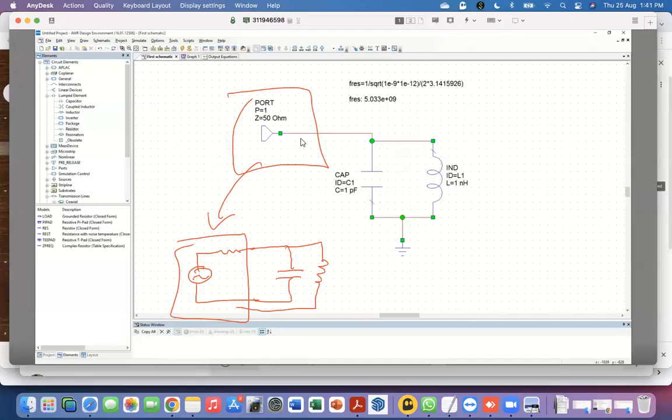Initially, when the energy is getting built up, there will be some reflection and some absorption, and the reflection will not be exactly 1. It's only after it has reached a steady state, which will correspond to whatever the voltage source value is and the 50 ohm resistor and the values of L and C. In the steady state, the amount of signal you are sending in is the same as the amount of signal that is coming out, and the energy which is present in the LC circuit is constant. So that's what steady state is.